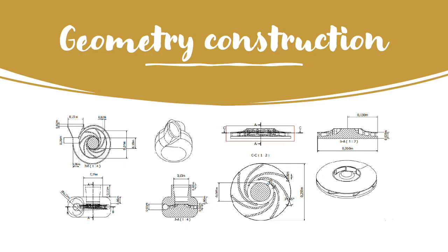After making the geometry design calculations, Autodesk Inventor is used to create a 3D CAD. First, the impeller is created. Data is imported to the program and using tools such as extrusion, revolution, and others, the impeller can be created. It is important to establish that the impeller's creation is critical because it will affect the pump's performance. Also, the impeller created on Inventor will be semi-open because this helps to eliminate some friction, making the pump more efficient. The pump casing is then created.